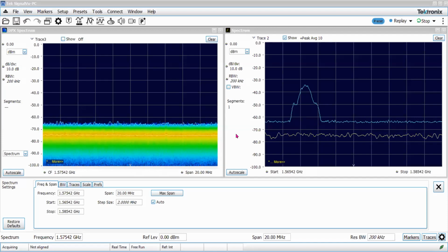So if you really want to see that type of signal coming up like this, what you have to put is a very high gain dish antenna on the rooftop that has a gain of above 20 or 30 dB, around 20 dB at least. You start from minus 130, so you have to come above the noise floor, that's minus 110.